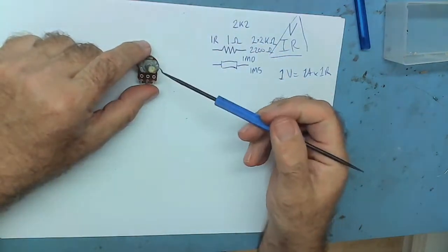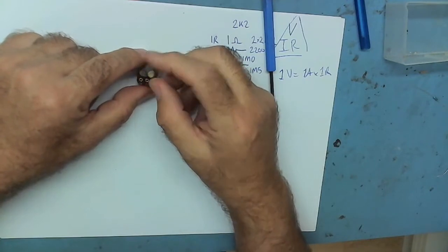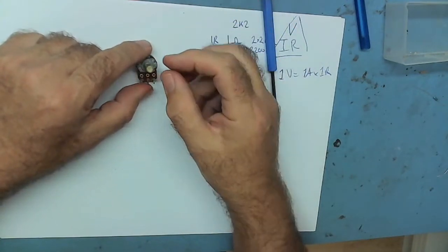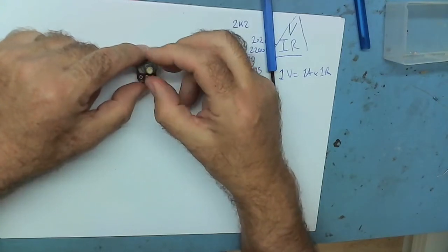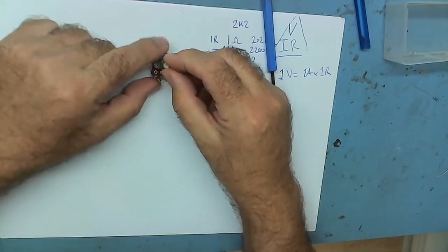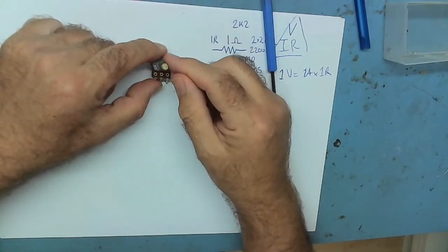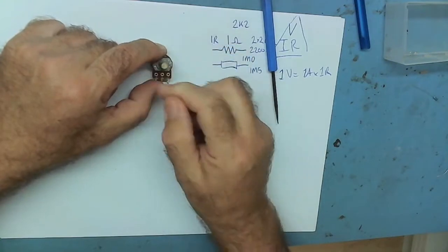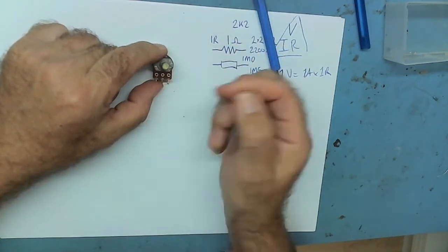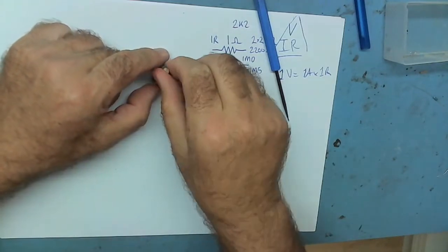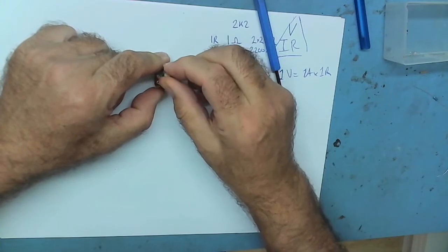When you have resistors like this, you have two main sorts. There might be more than two, but you have linear and you have logarithmic. So with a linear, say that's 100 kilo ohms from there to there, yeah? If I switch the wiper to this end, from there to there is 0. If I switch it to halfway, it's 50 kilo ohms. If I switch it all the way, it's 100 kilo ohms. If I go three quarters, it's 75. If I go a quarter, it's 25. It's linear, so the same amount of movement will always add or decrease the same amount of resistance.